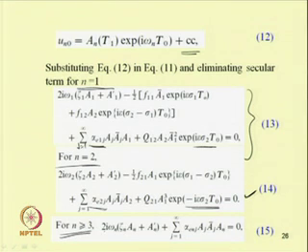So, this equation is written in this form: 2 I omega n zeta n a n plus a n dash plus summation j equal to 1 to infinity alpha I n j a j bar into a n equal to 0. And one can note from this third equation, that is n greater than or equal to 3, that neither forcing nor internal resonance cases are there. So, due to the presence of the damping term, the response amplitude will decay and the system will come back to the original trivial state for n greater than or equal to 3.